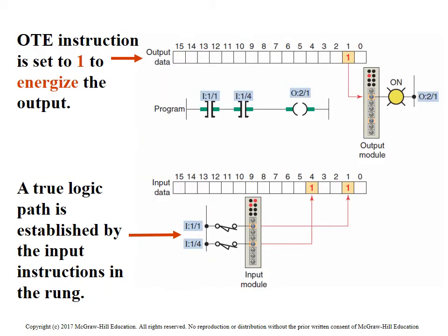As you can see here, we've got output 2, 1. I've got this contact in, this output's turning on. It's writing to this data table, dumping that information from this location right in the data table, and then this card is getting updated with that information, turning on the corresponding output. And here they're also illustrating the inputs.